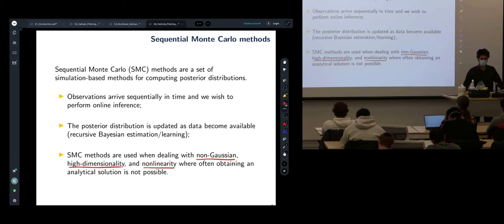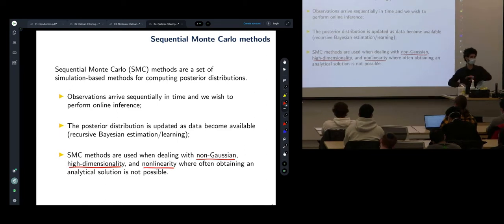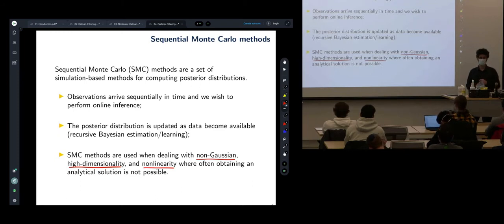Because as soon as you read non-Gaussian, well, you might want to look into the problem and see how non-Gaussian. A little skewed, maybe it's okay, right? If you're lucky enough to have access to some data and see the behavior of the system, if it's really multimodal, at one point in one place in the state space, another point completely in a different space, there's just jumping behavior, then maybe a Kalman filter might not be the best choice for tracking, because it will not be able to deal with this change of mode in the behavior.